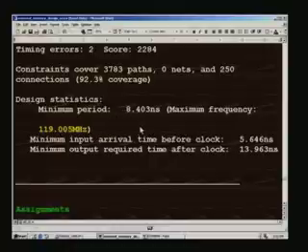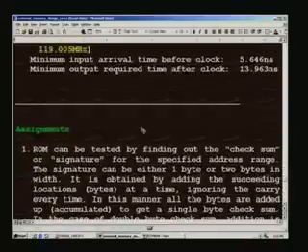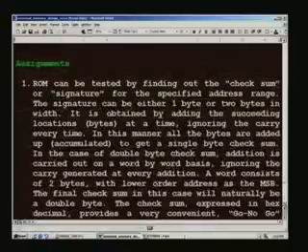So, we are justified in running at 100 megahertz, that is the clock rate is 100 megahertz, whereas the access is 50 megahertz. So, with 50 megahertz we can have actual RAM. This has been designed with the vendor's device taken into account. So, that means to say that is a standard RAM available, so that we may use later on in the actual project, that is 64K into 24 bits.